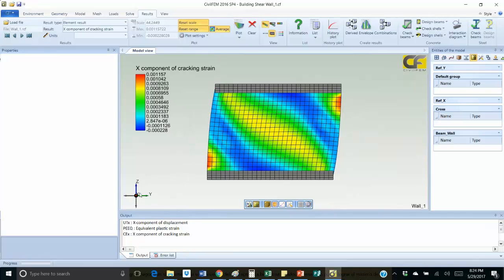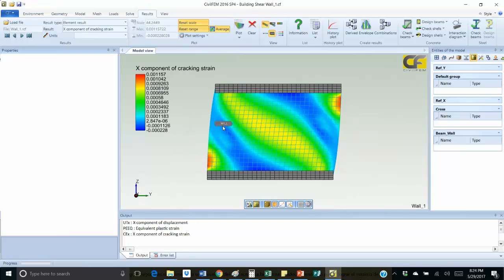So we can see that the vertical strain governing the condition is in the top and bottom opposite extremes, in the left bottom corner and the top right corner. So you can see the spread of the cracking, observing the minimum values in the blue area, and it maintains the contour in the yellow area, but the strains and the higher values are located once we make the displacement at the top and bottom right opposed corners.